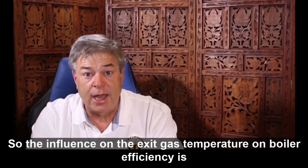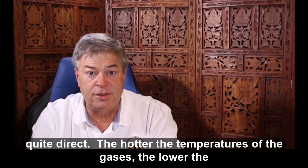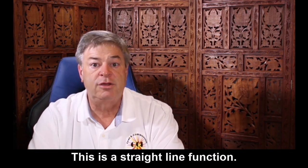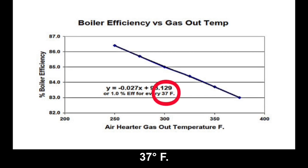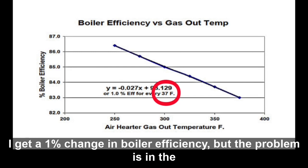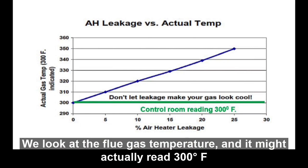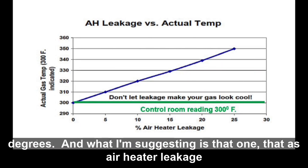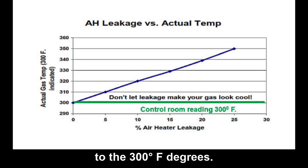So the influence of the exit gas temperature on boiler efficiency is quite direct. The hotter the temperatures of the gases, the lower the efficiency. This is a straight line function, and so when I look at the slope, I can calculate that for every about 37 degrees F, I get a 1% change in boiler efficiency. But the problem is in the control room, we look at the flue gas temperature, and it might actually read 300 degrees. And what I'm suggesting is that when that air heater leakage increases, you are actually diluting a higher exit gas temperature down to the 300 degrees.